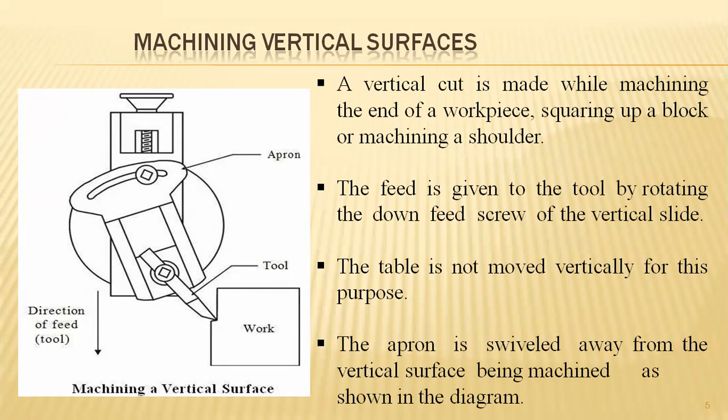So in the case of this pictorial representation, it is very clear that the feed rate will be given externally as the tool has a particular depth of cut at the tool and work part engagement, as displayed in the diagram. For example, 2 mm of removal or 3 mm of removal of material from the parent material will be considered, and the required shape of the material will be obtained.